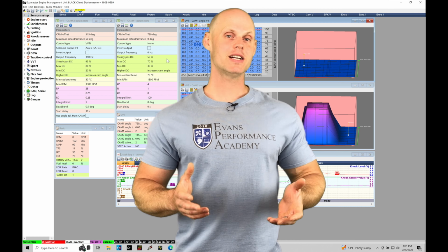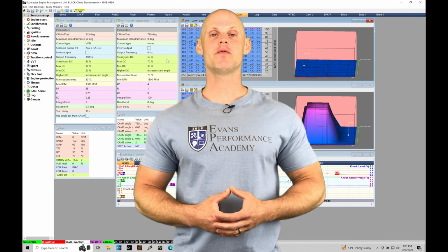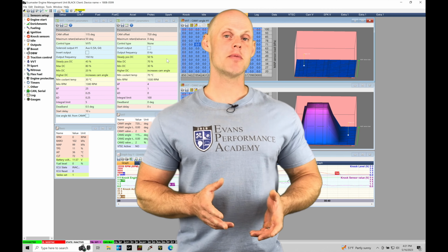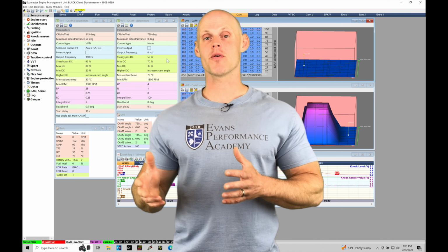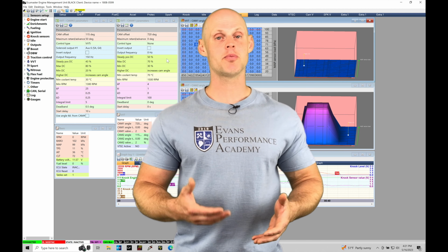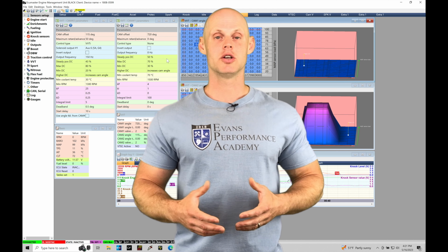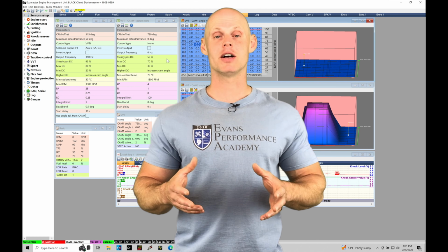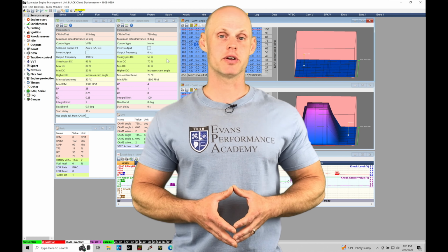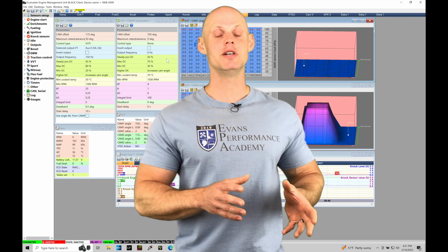Welcome back to part 6 of our live training session here with our K24 Swapped Civic Si. This training module, we're going to take a look at doing our high cam or VTEC tuning. We're going to look at our fuel, spark, and variable cam control, trying to figure out what is going to give us the best possible performance under wide open throttle conditions, and also in the part throttle VTEC conditions,